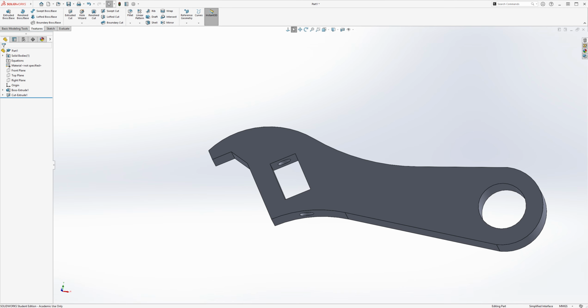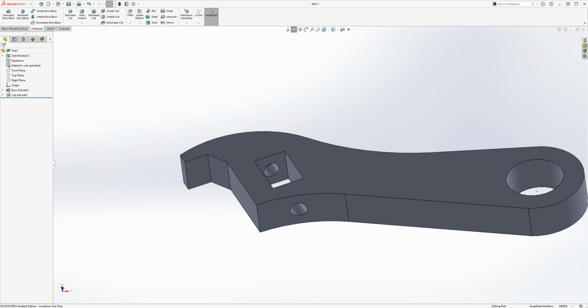Now that we got the hole, we were already looking at section view BB, but we'll look at it to finish the rest of the cuts. For the section view, you're looking from under the part and you're looking upwards, up and to the left.